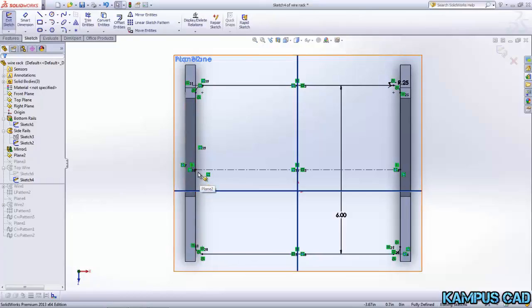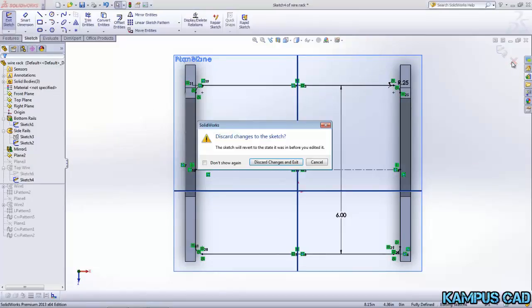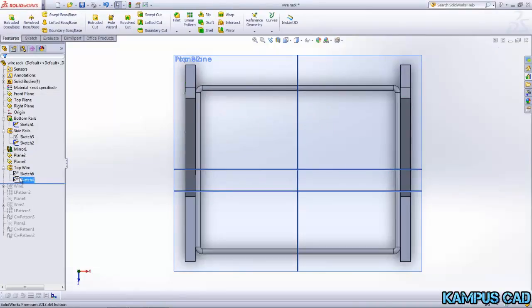And for the sweep, I imagined my cross section is going to be tangent to my profile, but I could have drawn it offset and had it in the center there. You have a lot of options. It's personal preference again.